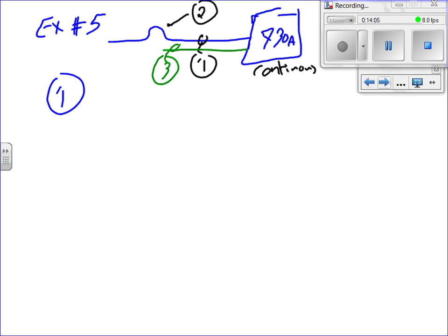What did we say? Number 1. We need conductors. Branch circuit conductors. Oh, by the way, when we size a conductor, if I ask you to size the conduit for the conductors, would it be hard? We just did that. If it's 3 conductors per conduit, can you find a conduit? What conduit, Chad? EMT? What insulation, Chad? It's THHN. You can size the conduits right away.